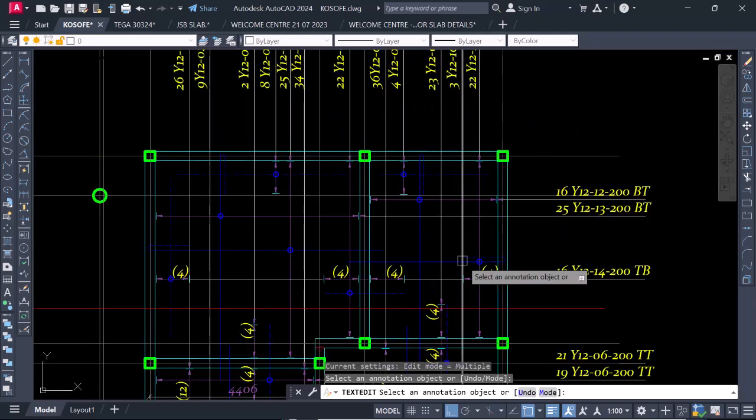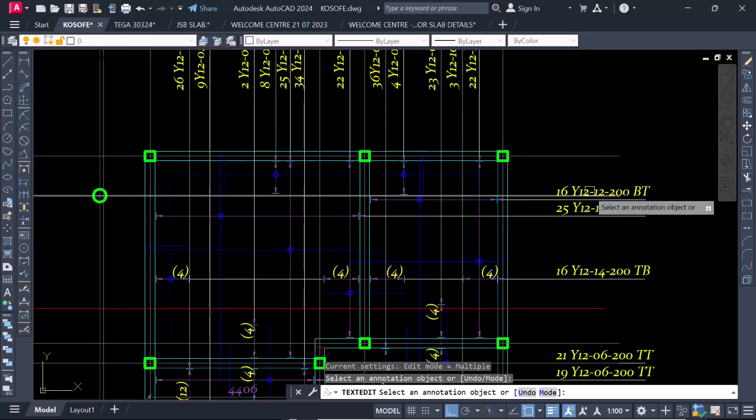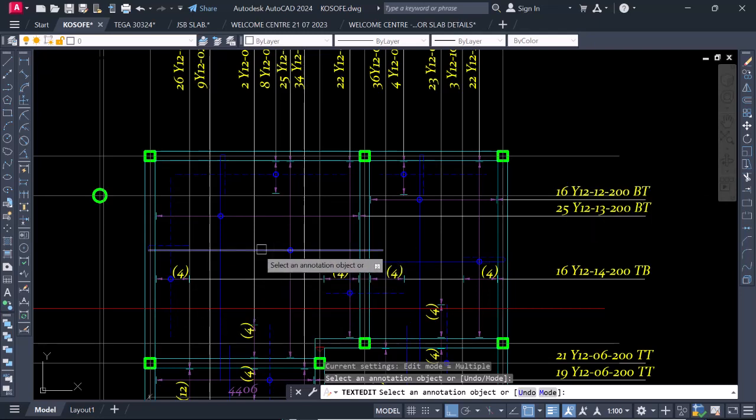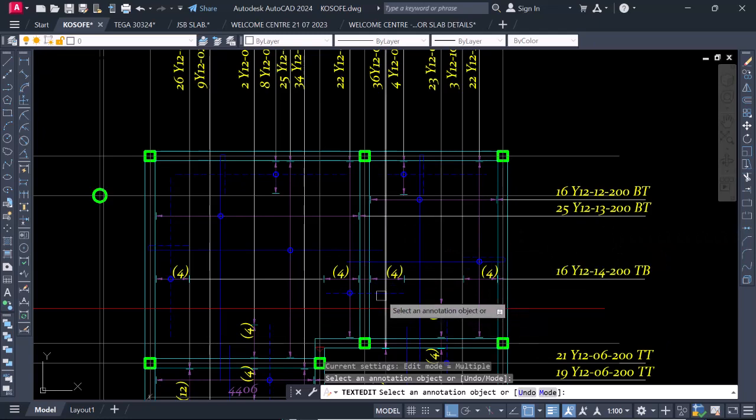So let's go again so that we get it. You can see here I have 12, and this is the bar. This is the rebar spacing across this line. When I cut this section, I'm going to see this as a line running across the span, so it is 12. If I also cut this section, I'm going to see this line running on top, and it's 13. So that's what I'm trying to do. The same thing here.